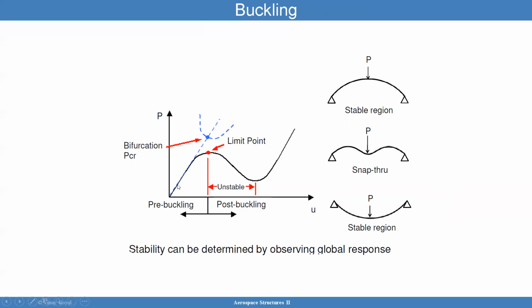Here in this picture, what you see, again, is a load versus a deflection. And here what we're measuring now is the deflection of the load application. So at that point, how much it moved downwards. And so that's what we're going to be looking at now. In this case, you apply a load P, and it starts stable. Nothing's really moving much. It's moving linearly with load. As the load is increased, this point is moving downwards in a very stable way.